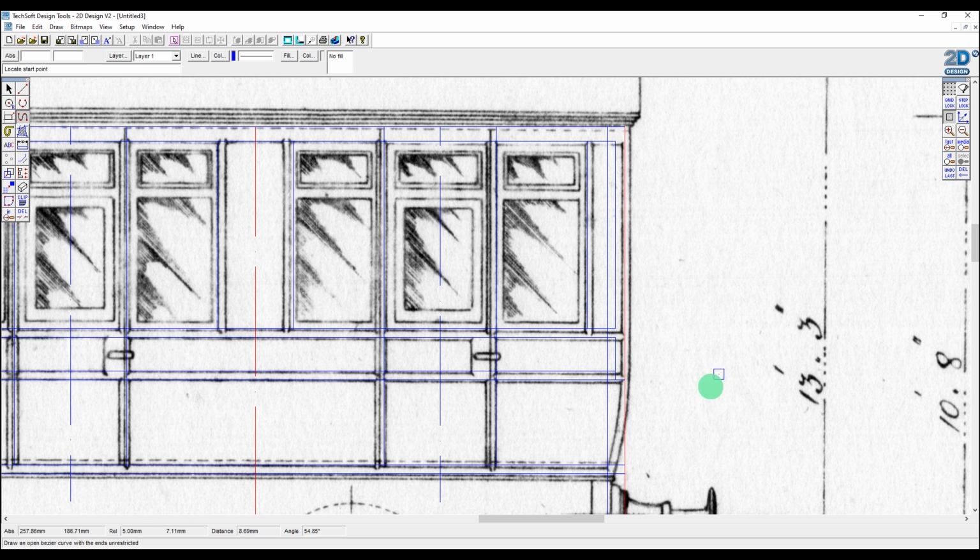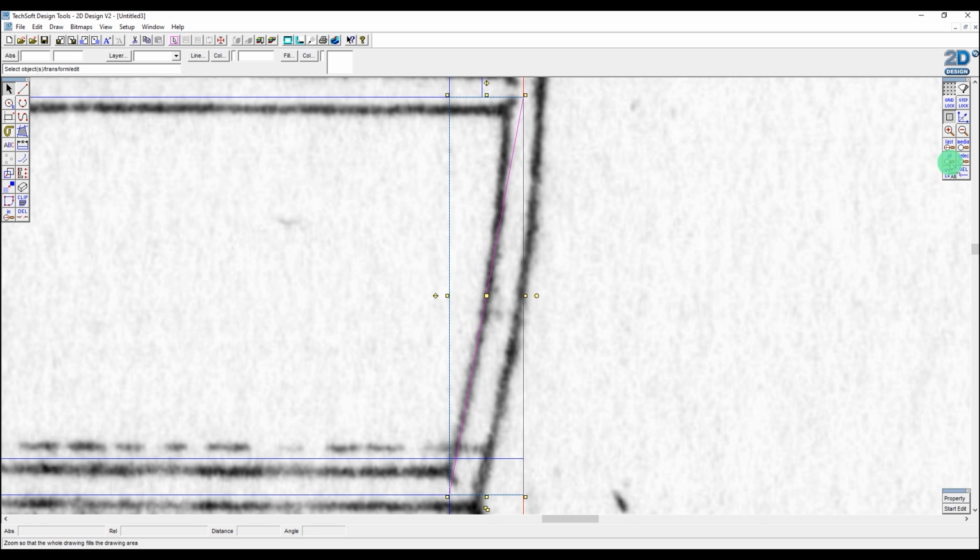And to do that I'm using a tool called the Path tool. Now often you'll see my mouse disappear off to the right hand side of the screen, and that's turning on an attach tool. I'm toggling that on or off. And where I want 2 lines to meet together perfectly, we can select the attach tool and our new line that we draw will automatically tag itself onto one that's previously been drawn. That's a really useful thing to do, very important.